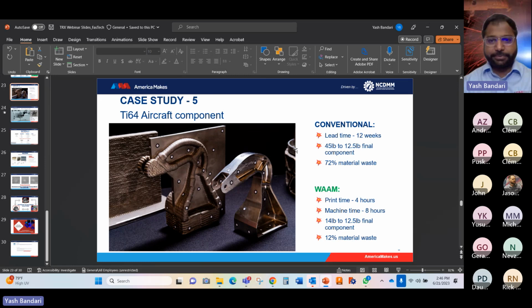So, like I said previously, we also think about the machining side as well. So you would need something to get clamped to, right? You wouldn't think of it when you're printing, but when you go and apply it in a milling or a lathe machine turning center, then you would think, oh, okay, this is missing. So in order to reach every corner of the printed component, you would need some kind of tooling, right? So that is why we put this extra feature, so that it can be clamped, and then every other point, the tool can be reached for the machining process. So it's just for seamless machining operation.